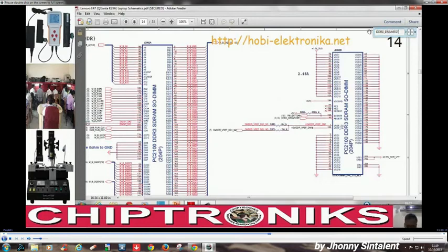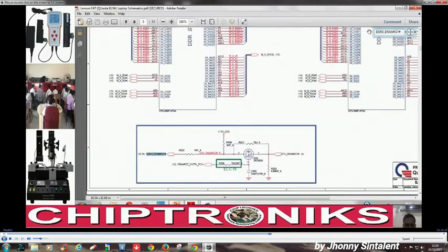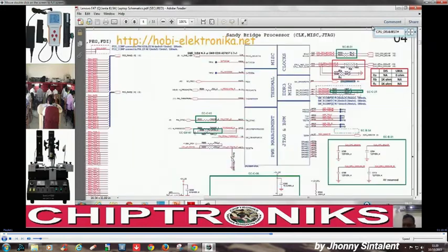DRAM RST, right? And this will come from, you can see, CPU_DRAM_RESET, which is the same as DDR3_DRAM_RESET, and there must be 1.5 volt. This is 1.5 volt connected, and you can see DRAM RST has, and this is coming from the DDR3 section of the CPU.